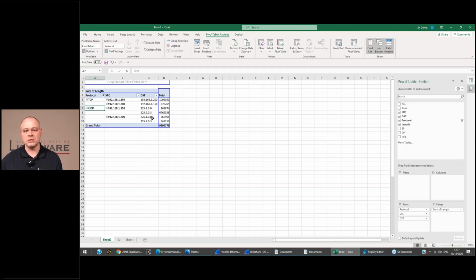If you saw more of these multicast groups on this screen, with different numbers, then you would immediately recognize that something's not right. If I have a pair of Vinx devices and they only communicate on this ID 3, I don't want to see an ID 1, 2, or 4 as other video streams. So if you take this little table and send it to the support team, they would be able to help you a lot faster to see what's going on.